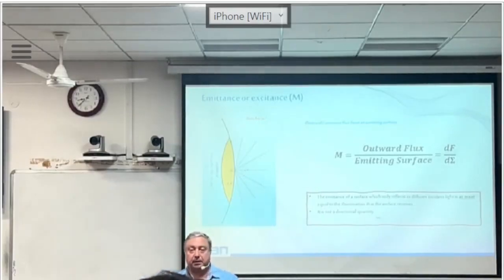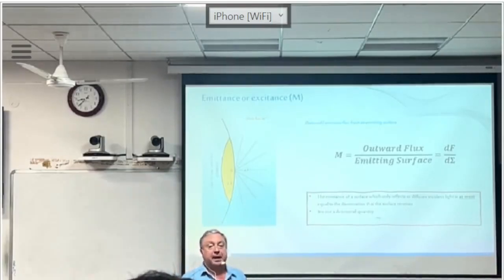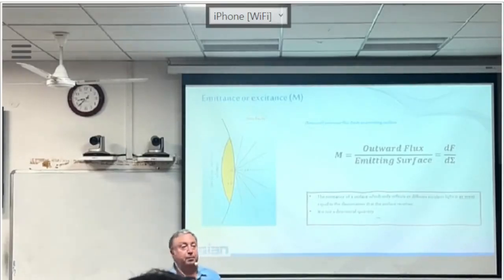You will see that at the end of this lecture: between the illuminance that arrives on the table and the emittance of the table as a secondary source, you have the reflection coefficient of the surface. The reflection coefficient could be equal to 1 at the best, and then emittance equals illuminance, but in many cases the emittance is lower than the illuminance.